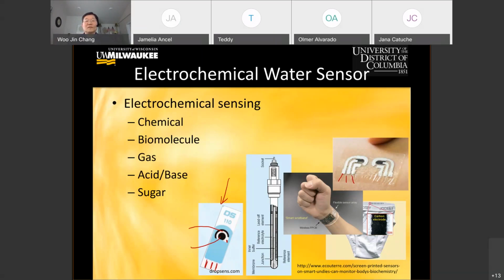The major issue in electrochemical sensing is the development of the system, the reactions used to detect the target molecules. That is typically done by treating the surface of this active area to modify the surface of this electrode, so this sensor can be used to detect different molecules when the treatment is different.